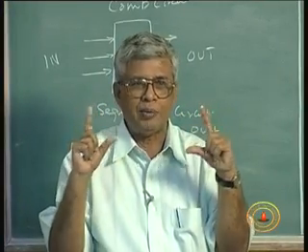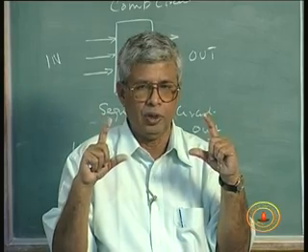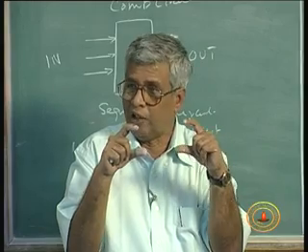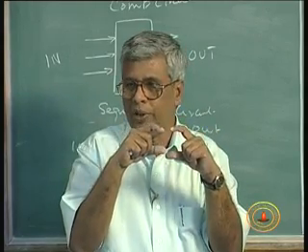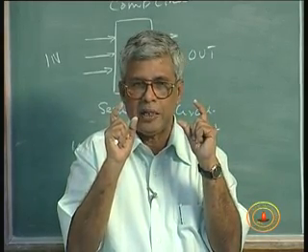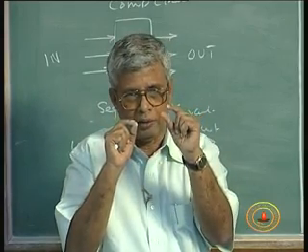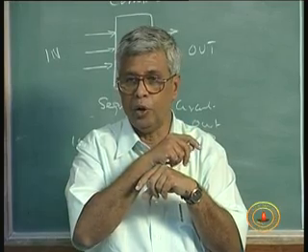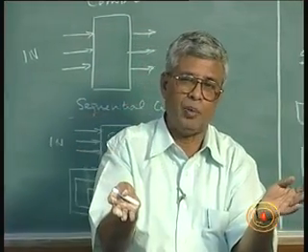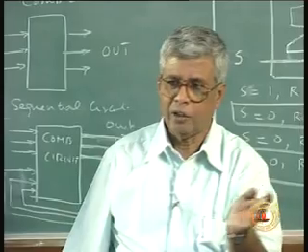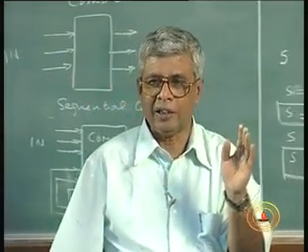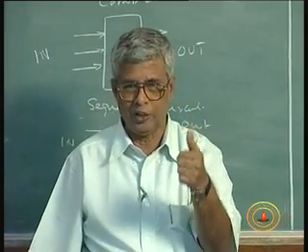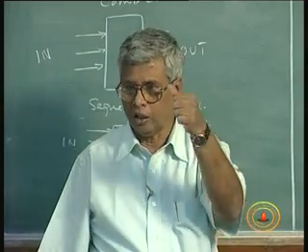Did I introduce a new concept here? No, in the sense of new theory or anything. There are only 2 circuits, 2 gates which you know the behavior of, and we used them in a way we wanted it. So, combinational logic, the basic building block NOR gate, which is a universal gate by the way, is used also for memory. In every circuit including combinational and sequential, all circuits can be formulated or designed or implemented using AND or inverter as the general case, or in a specific case of universal gates NAND or NOR.